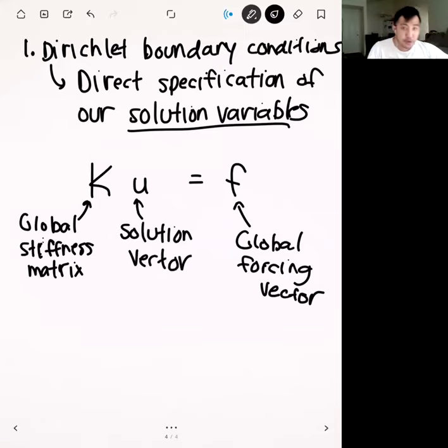Okay. And so usually for a lot of these finite element problems, all the entries within the solution vector represent the solutions to our problem at all the nodes in our system. Okay. And they're usually all of the same type, or they're all very similar types. And so for the direct stiffness method that we've been working with, everything that's in the solution vector has units of displacement. Okay. And then when we're doing beams and frames, we also include rotations in here too.